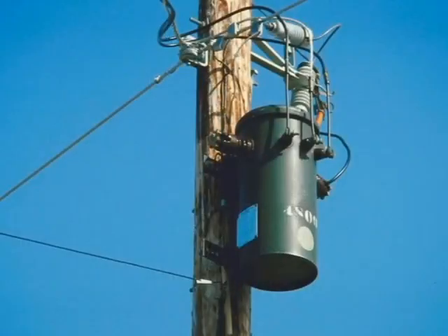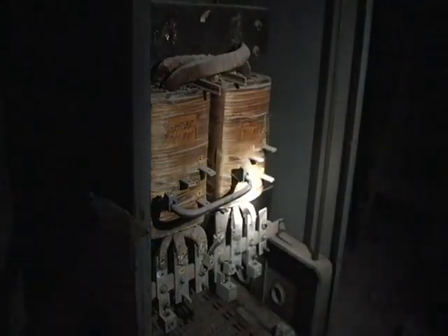Something else that you can encounter when you're doing work in old buildings, even though you're the asbestos guy, you should be somewhat knowledgeable about other program requirements as well. This is an example of a dry electrical transformer as opposed to a wet one. The wet ones, you'll find the PCB containing dielectric transformer oil. This one does not. This is a dry unit, doesn't have the oils in it. It's just to let you know, one kind of something you can run into.